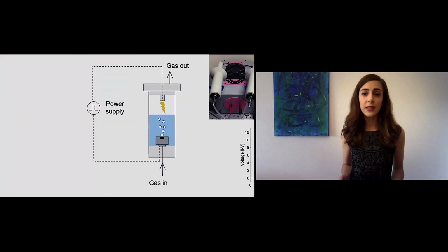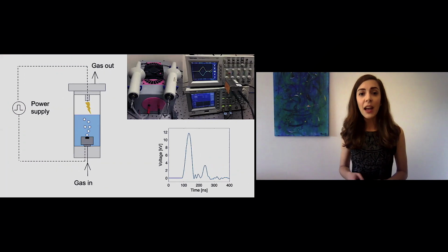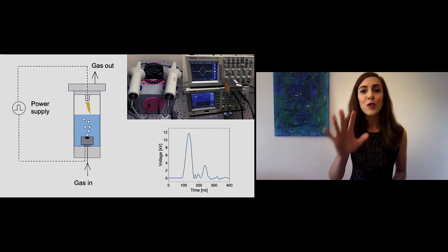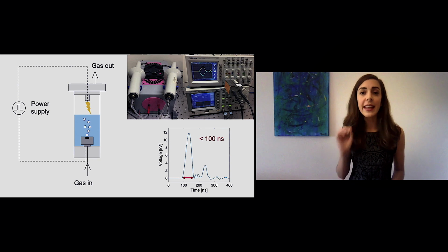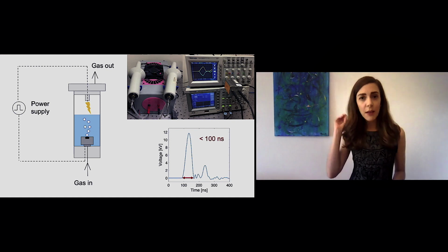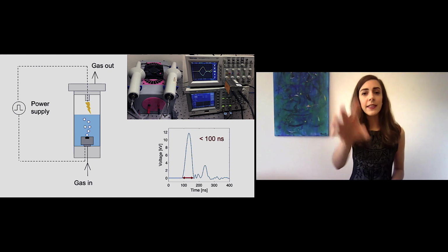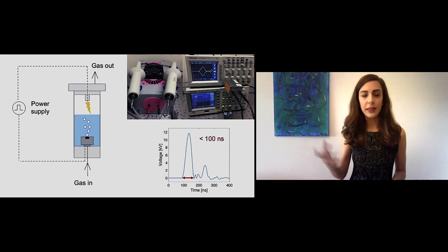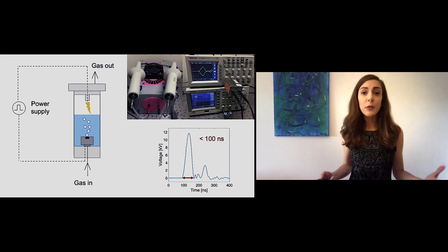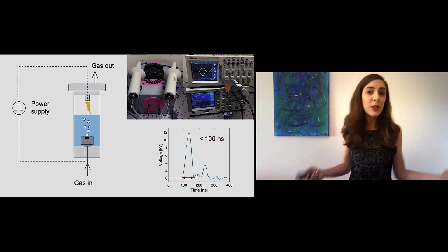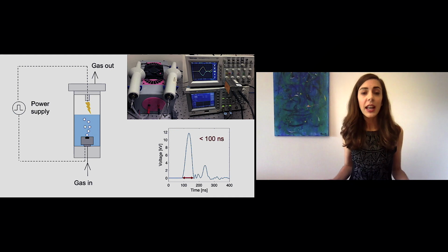In order to achieve this, what I do is that I put high voltage pulses that are high enough to start the chemical reactions, but then I stop the voltage pulses really fast, in less than 100 nanoseconds, before the water gets heated up too much. And I repeat this again and again over time. So high voltage starting the chemical reactions, and then stopping it very quickly, before the water gets heated. I do this 3,000 times in 1 second, which means that if I was doing a water treatment over the duration of this presentation, I would be putting in about 3 million pulses.